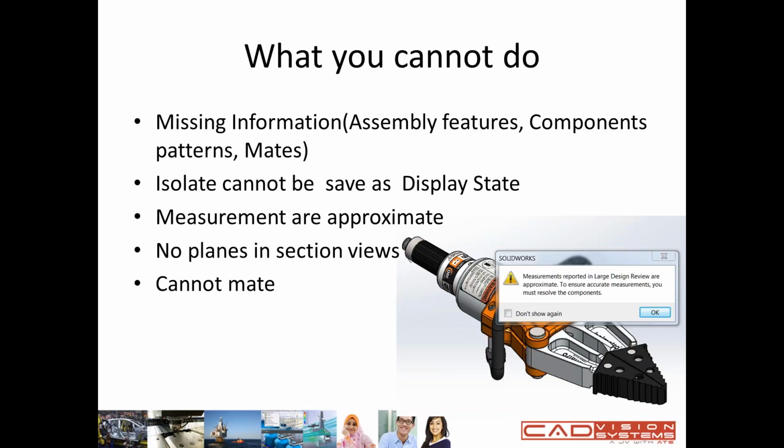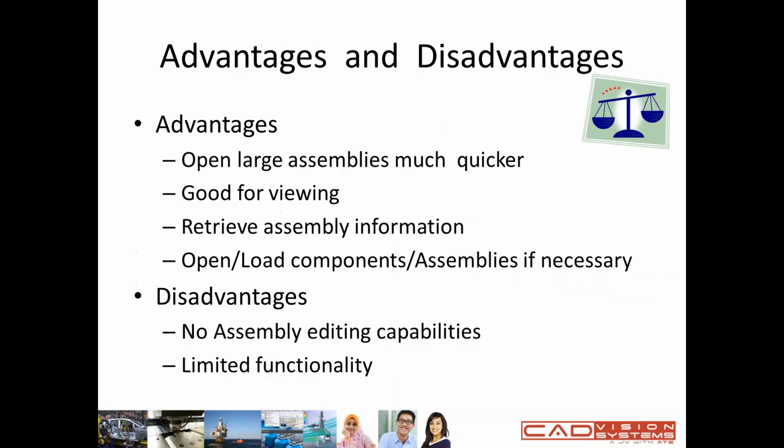Okay. To the next one, about the advantages and disadvantages of Large Design Review. The advantage is that you are able to open the large assembly in about a quarter of the time, compared to a fully resolved assembly. You can reduce it to a quarter of the time. You just need a quarter of the time to open a large assembly.